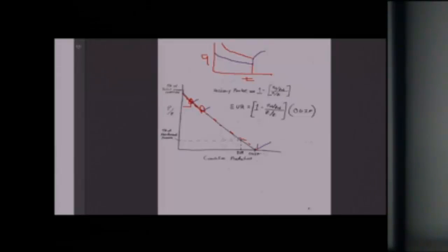So initially, remember when we were making up numbers in class, I just assumed it was draining 640 acres, and so we calculated the gas in place for 640 acres. This way, I can actually calculate the real drainage area, utilizing material balance. So we're going to always kind of use material balance. Petrophysics is where I get my porosity. We're not going to actually practice petrophysics, but anytime we have porosities and saturations and heights, that's coming from well log data. Do you still have to assume either an abandonment pressure or a recovery factor though?